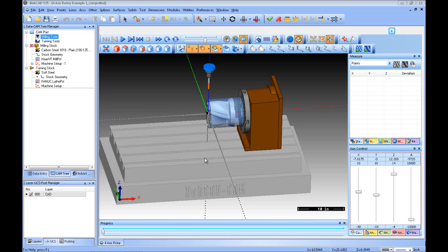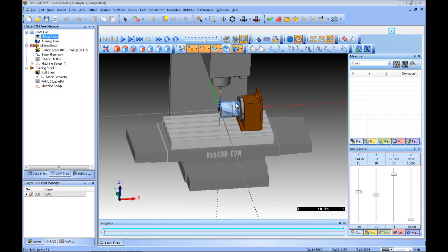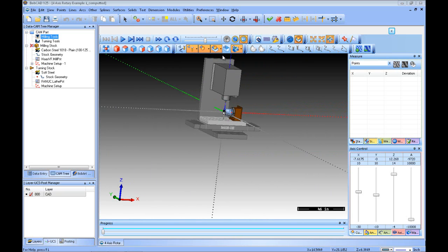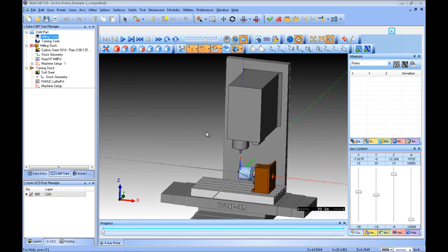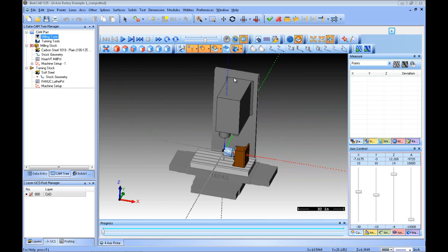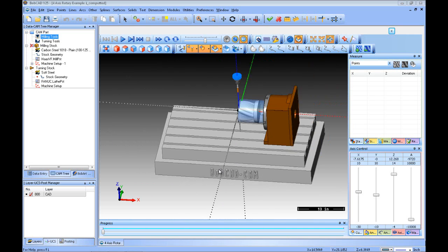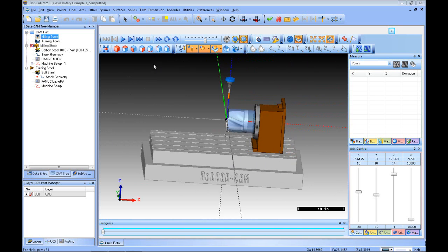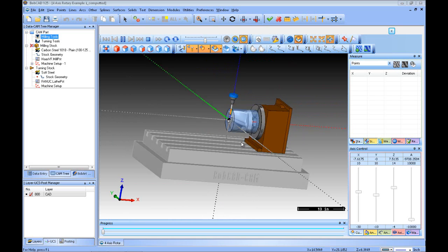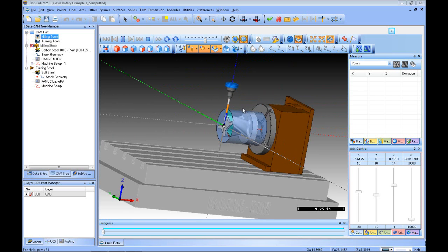We didn't have the M underscore H with them. The rest of them are turned on and off by a button, and that's this one here, which is machine housing. That's what the MH stands for. If I turn that on, you can see there's the rest of my machine. And the nice thing about that is if you don't want to see it all the time, if you assign the M underscore H at the beginning of the geometry, I can make it transparent or turn it completely off. And now I'm just looking at this area here, hit play, and I can watch it cut.